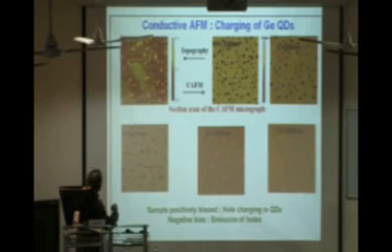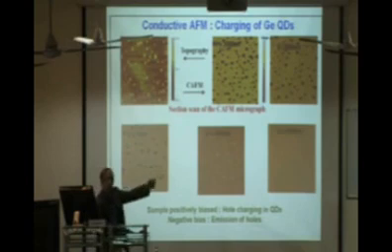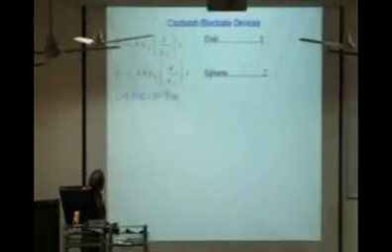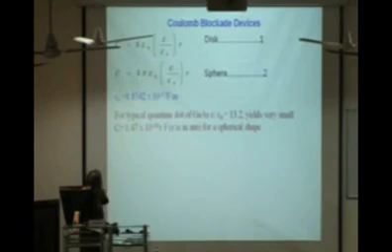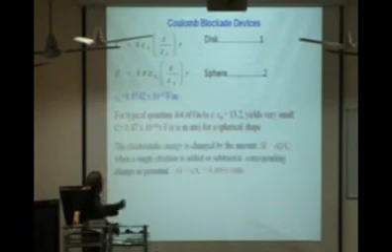Of course, there is some charge leakage, but still it shows that. But when you apply a negative bias, only then can you remove some of these electrons from these quantum dots. That shows that these quantum dots can be used for single electron memory or single dot memory devices very nicely. In fact, if you do a calculation, take the size of each quantum dot, and ideally, if